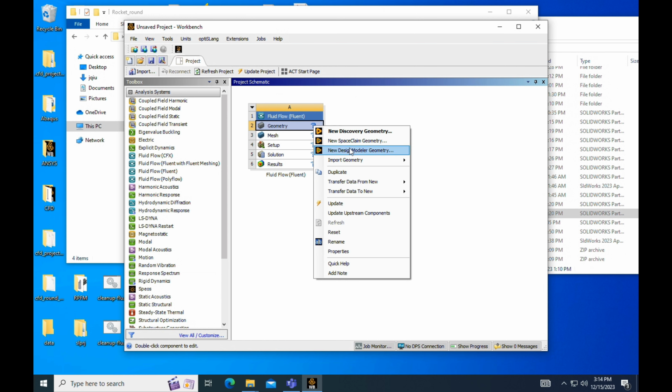Now we'll use the Boolean tool. We're going to put subtract right there, and we're going to select the innermost rocket body. There we go. Oops, I had a little bit of a mix-up right here. There we go, accept. Then we select the region that is outside of that mesh. And we're going to generate.